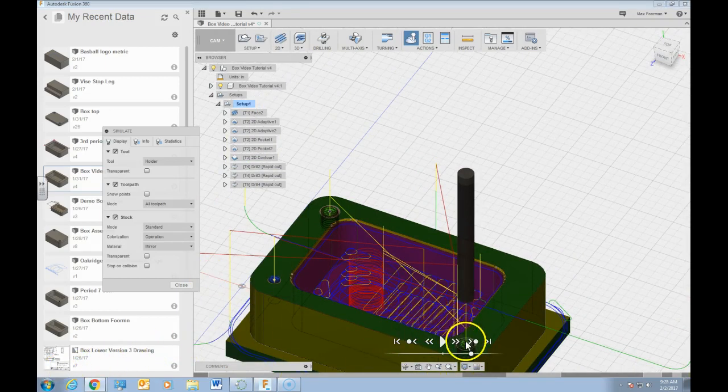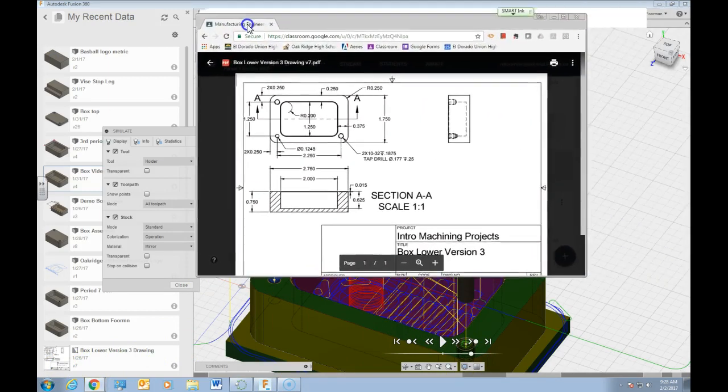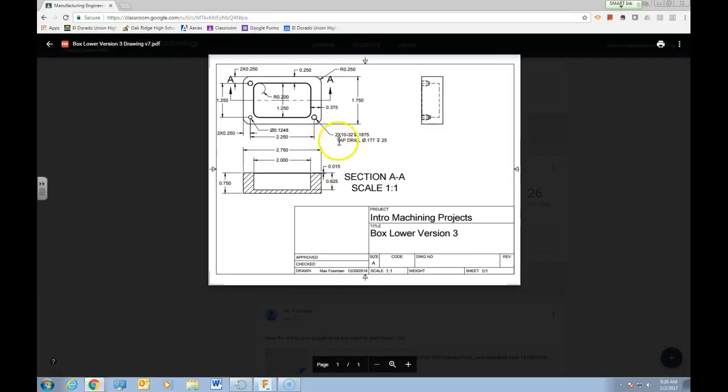So if it's only drilling to that point right there, I need to actually come back and refer to the drawing itself. We need to make sure that that tap drill goes to a depth of 1/4 or 0.25 inches deep, because we need to make sure that we're going to have space to come in and do this next operation here that's a tapping cycle.